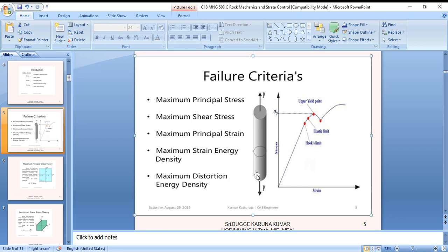Generally, the well-known relation between a component of stress and the strain has been established by experimentation. These relations are known as Hooke's law, assuming a rectangular parallelepiped with its sides parallel to the coordinate axes, acted upon by the normal stress sigma x uniformly distributed on two opposite sides. The magnitude of the normal strain epsilon x is given by sigma x divided by E. There is also Poisson's ratio, which can be calculated from the basic differential equations.